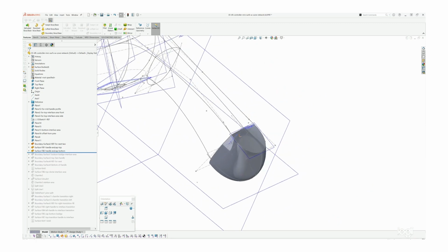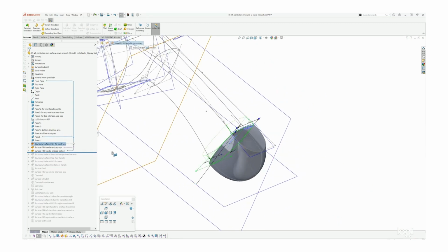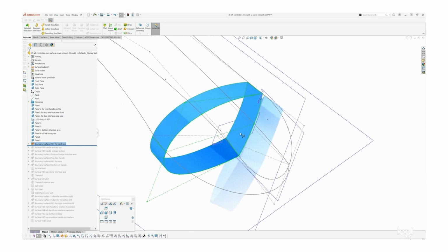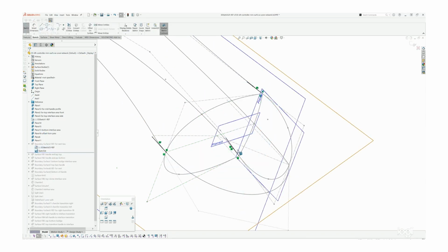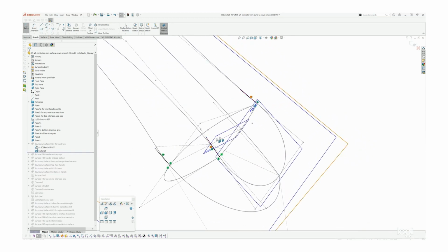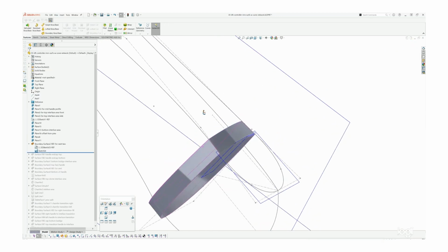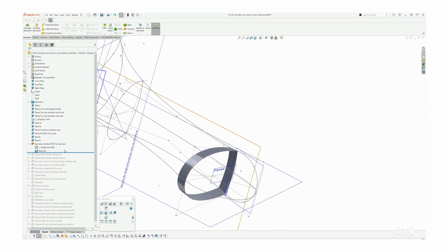Here we created this end, but you'll notice that what that's built on is a boundary surface. And that boundary surface is really pretty simple. It's basically two sketches. They're these 3D sketches that are just simple lines that are all equal to each other, and they're all constrained tangent to this existing curve network. With that, now I can control the direction of the way my boundary surface flows.